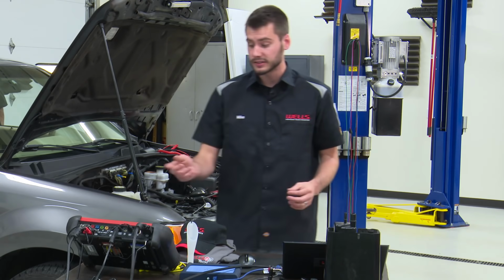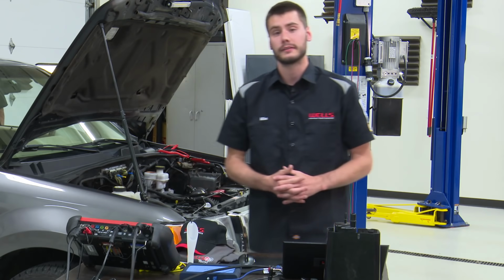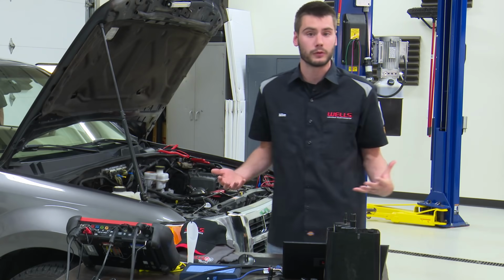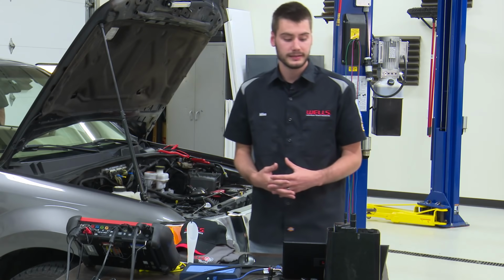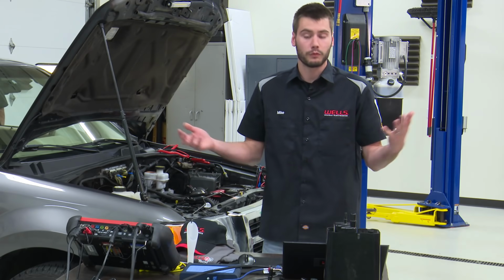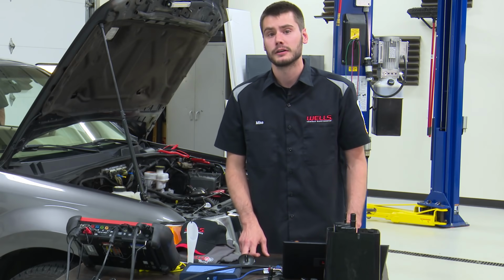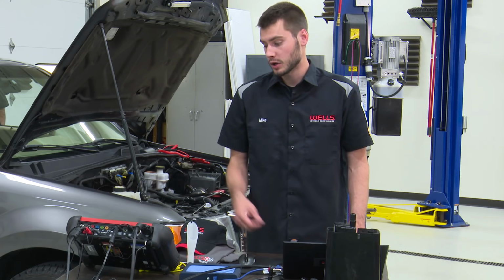So if you have single digits in there, you might have to go out and drive the vehicle for the customer because they might not meet those conditions. They might not go above 40 miles an hour. They might not, for whatever reason, any of those conditions might not be met. Intake air temp, 40 to 100 degrees. Is this going to run?